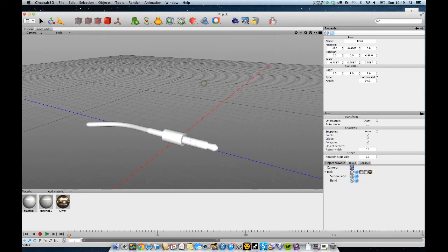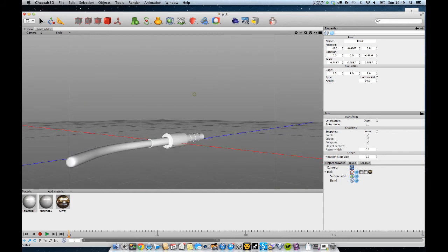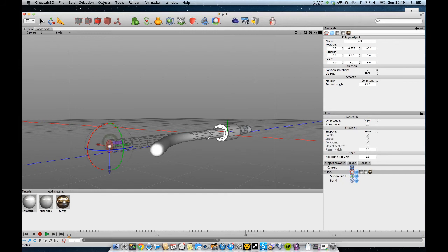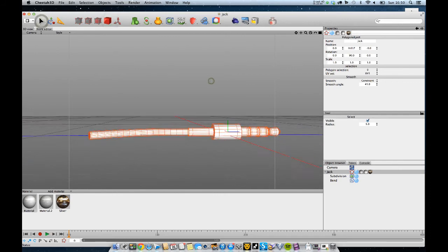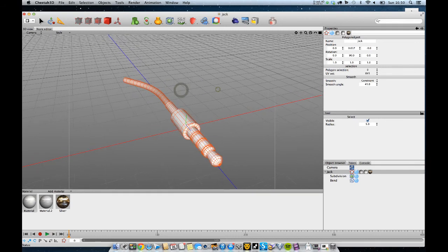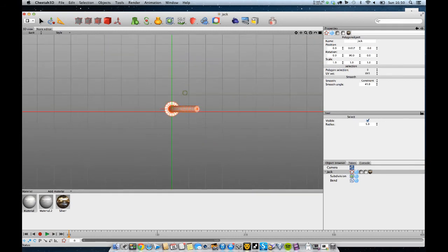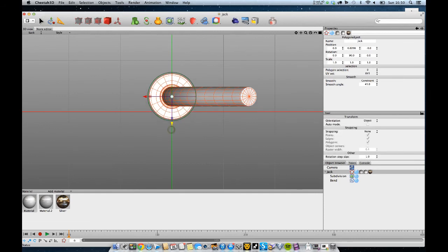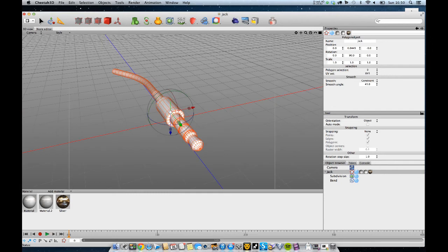That's cool. Just spotted one more thing there. You can see the subdivision taking over a little bit on these edges. So I'm just come into polygon mode just down here. I'm going to select these and call inner extrude on them and just pull in just once, just very slightly. There we go. Giving us a harder edge. I've actually never rendered anything on this new machine yet, so it should be quite interesting. Object mode. Just going to raise this up just a touch so it sits exactly on the floor.